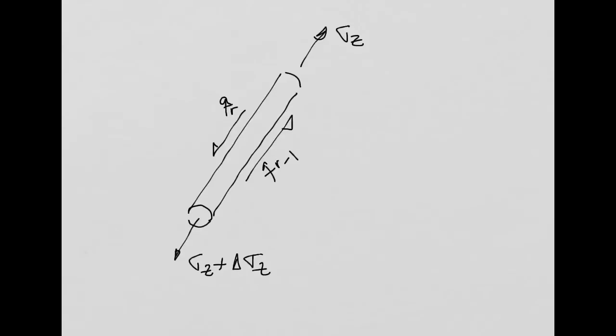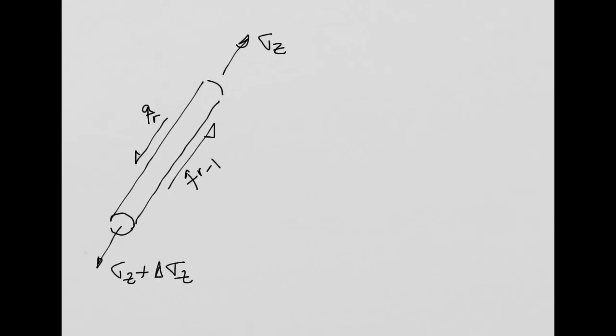So we have our boom here with all the stresses, the shear flow, and the direct stresses applied on the boom. So this is our free body diagram now. There's one more thing I need to include, which is this dimension here from here to here. Let's consider this infinitesimal length delta z in the z direction, okay?